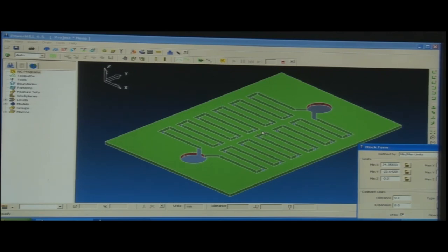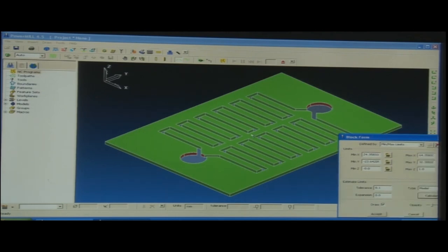Center would be the center of the x and the y direction both, and also the z, meaning the perpendicular direction, the tool has to touch at the center of the workpiece. So, it is more convenient to take the center of the machine, because that helps us a lot, because also this job is symmetrical in both the x and y directions. It is better to take the center.